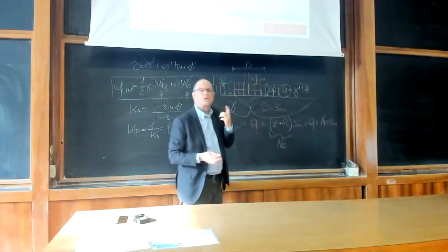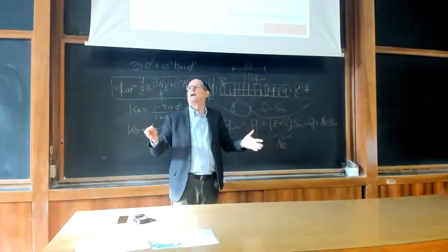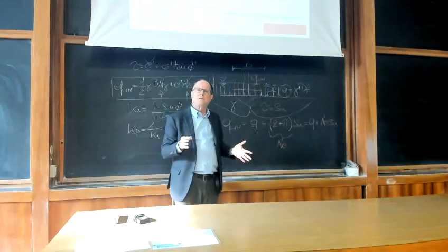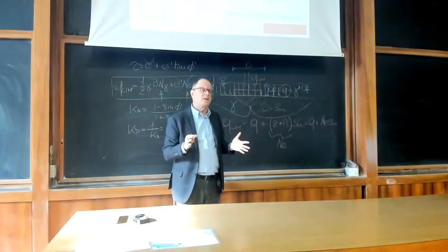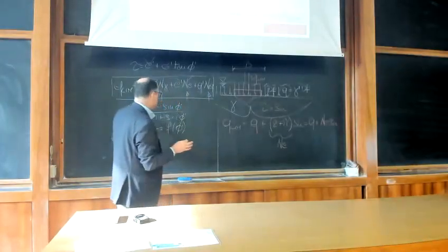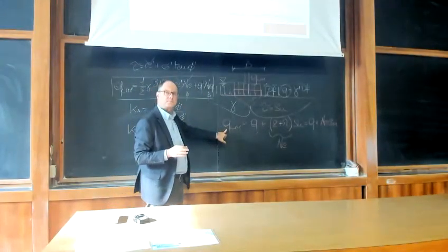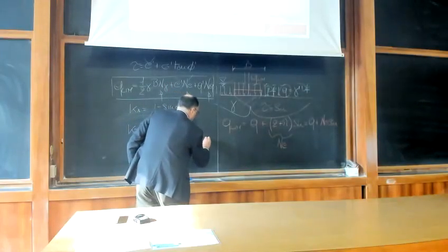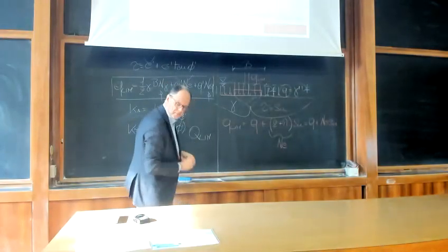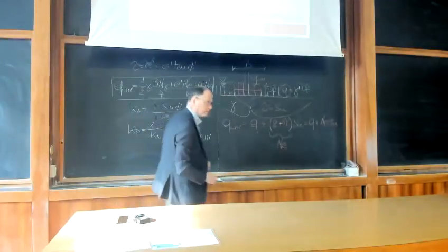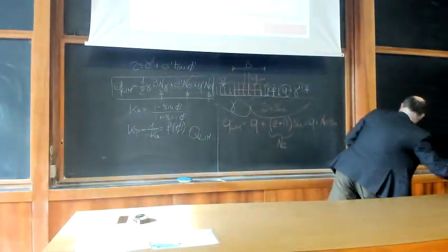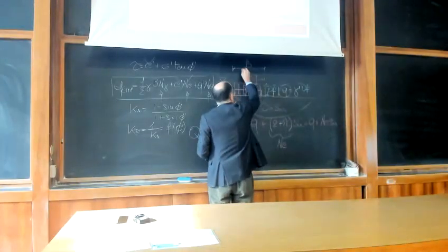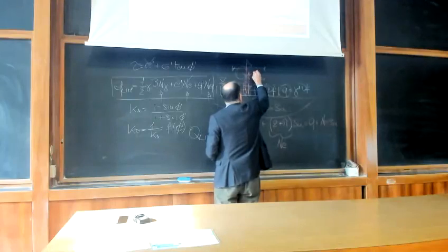So you say, well, of course, if I have a larger footing, I'll have a larger bearing capacity. This is not exactly what you have in mind, because this is a unit pressure. So the maximum load that you can apply here, the maximum load in terms of force, this is a Q limit.